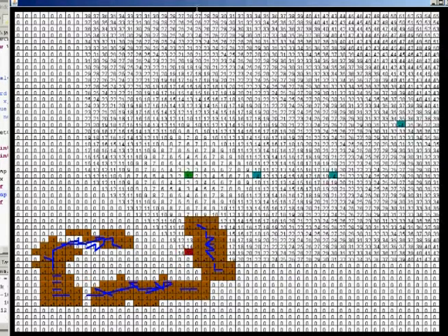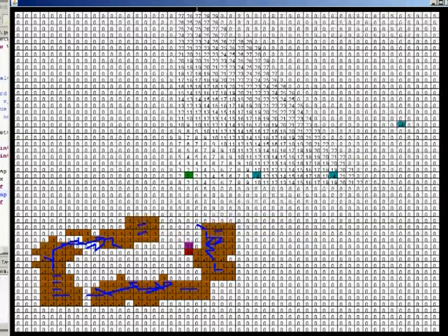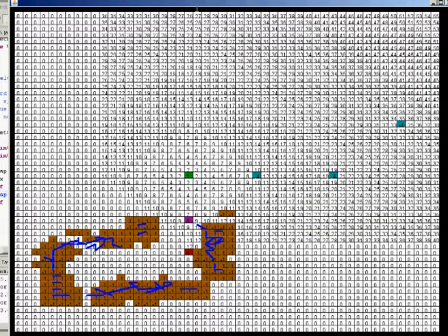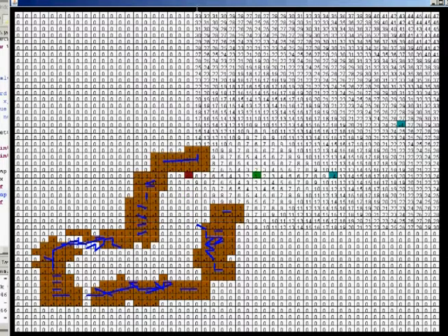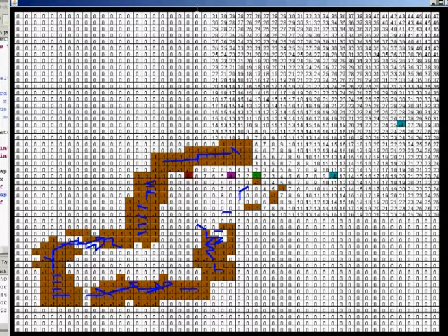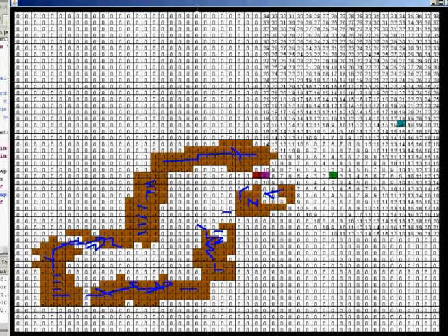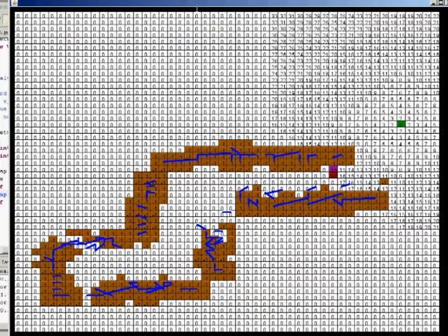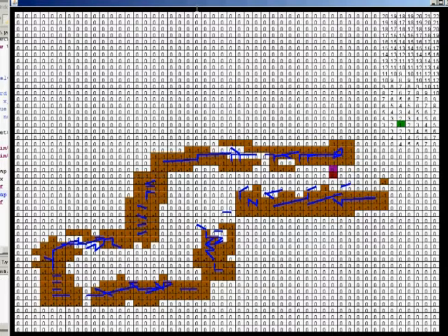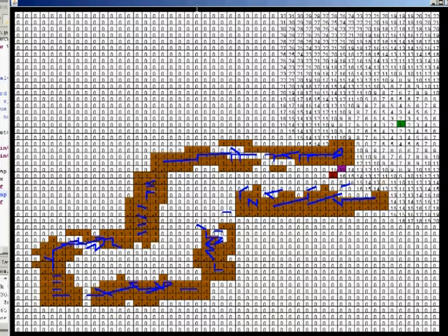We were able to detect obstacles, and we can avoid obstacles while we are heading to the next waypoint or going back to the home position. We also have what is called the escape function. When it gets blocked off, when it realizes there's some obstacle blocking the path, for example because of our line mapping it blocks off all the paths and it can't go anywhere, it gets stuck in the same position in a forever loop, then it's going to use the escape function.